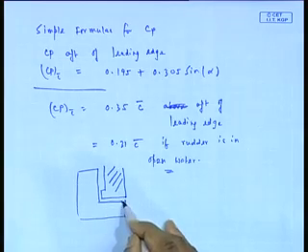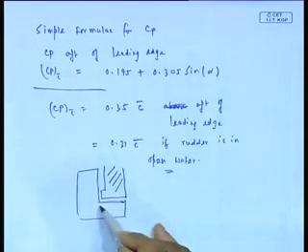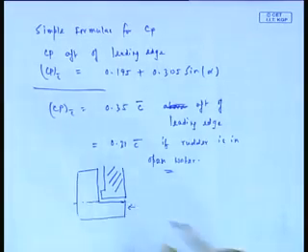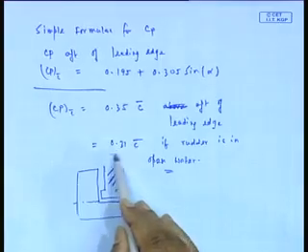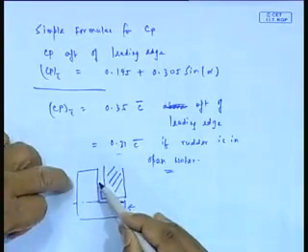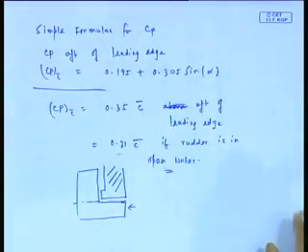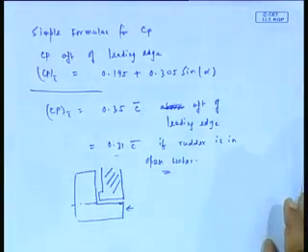Why do I mention this? Because for this bottom part of the rudder, this face is facing water directly. So for that, CPC will be 0.31 C bar, whereas for this part which is obstructed or has something in front, it will be this. So these are all simple empirical formulas.